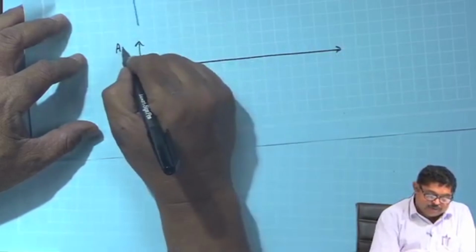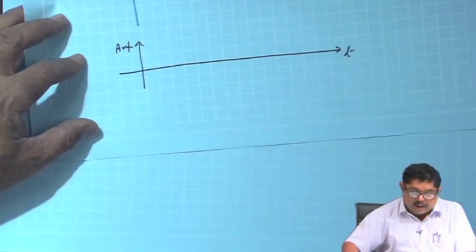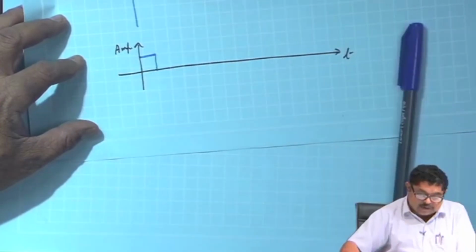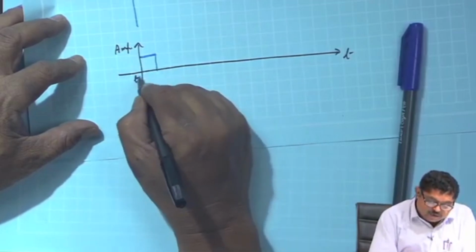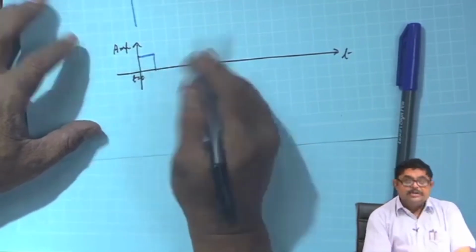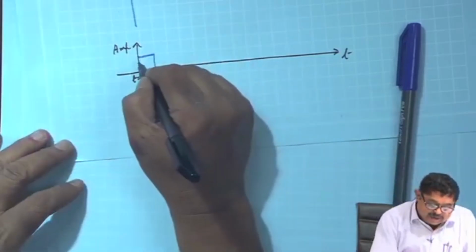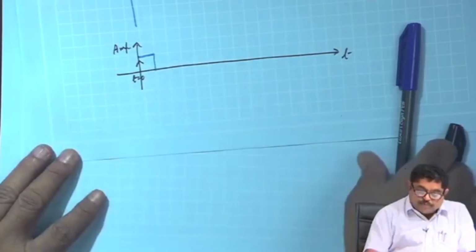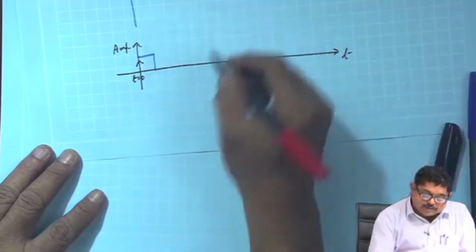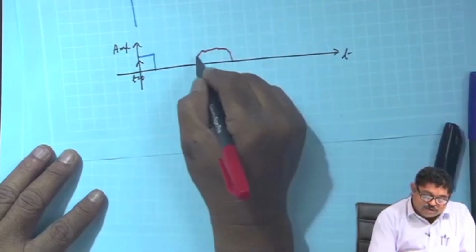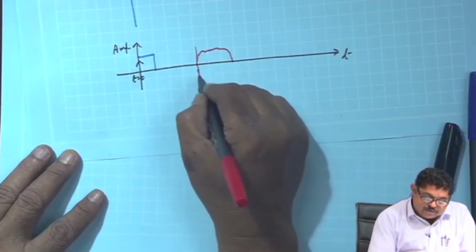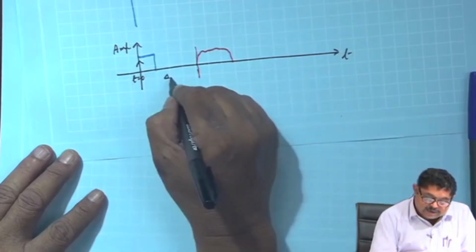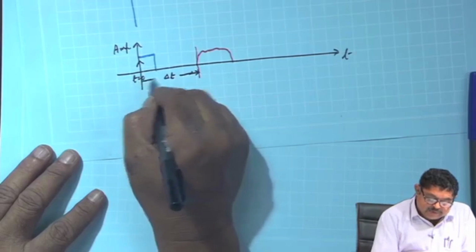Again this same graph, amplitude versus time. I have this transmitted pulse, let me say it is given at t equal to 0. When I am sending the pulse, let us say this rising edge of the pulse is my reference. Suppose the echo has come here, so this rising edge is here. I will measure this difference of time.